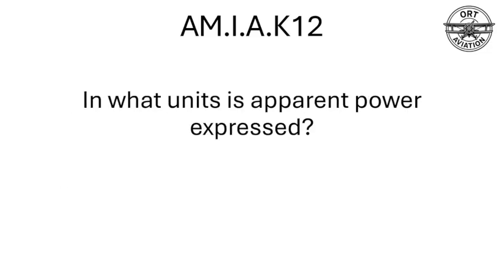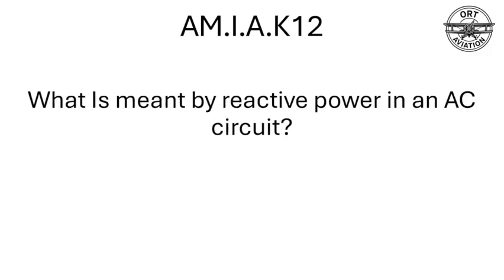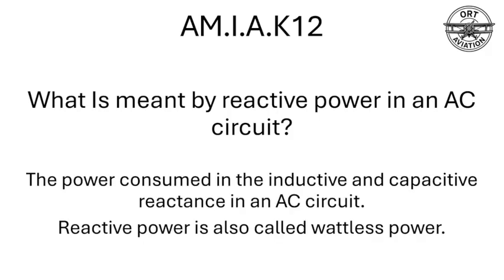In what units is apparent power expressed? In volt amps. What is meant by reactive power in an AC circuit? The power consumed in the inductive and capacitive reactance in an AC circuit. Reactive power is also called wattless power.